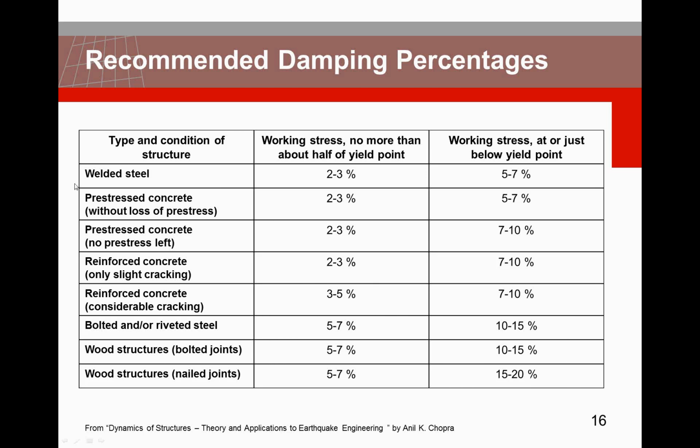And of course, for many of our users, the range with the reinforced concrete and pre-stressed concrete is of interest, and you see, depending on the loading, it will be between 2 to 3 and 10%. So quite often 3 to 5% is used as a starting point, but may be adapted due to specific needs or specific loading conditions.